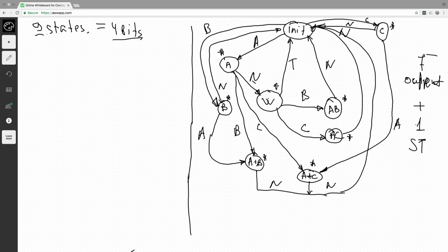So we want to mark state W with the asterisk character to introduce an additional output that will be the start of the timer. And the timer will be started, and once it is expired, it will generate the signal that will come in. So the timer is an input signal, but it is not a signal generated by our keyboard.